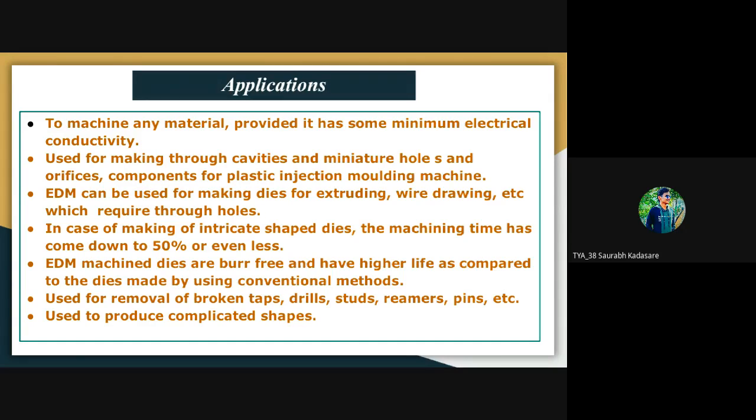Again, using this process you can obtain a matte finish during this EDM process, by minimizing the polishing time. Then another common application of EDM process is for the removal of broken taps, drills, studs, reamers, pins, etc. For the removal of these, we can use this EDM process. Then by using this EDM process, one can eliminate hand work.